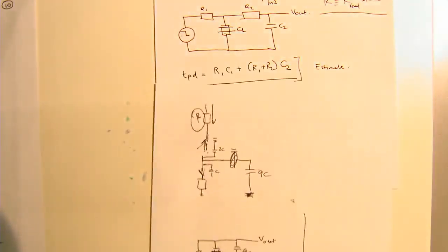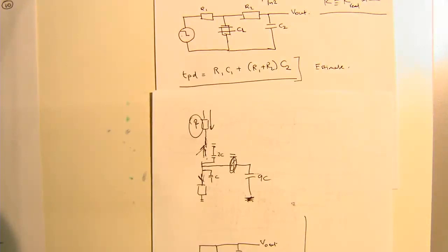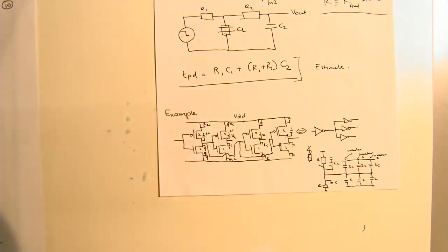I just wanted to make sure, because otherwise you'll see 2 R's and you're going to say, where did Stan choose that R from? Is that from the NMOS device? Is it the PMOS device? I also wanted to emphasize that depending on whether it's a rising or falling input, a different transistor is actually contributing to the current or to the output of that signal. So I just wanted to make sure that you guys are aware of that.